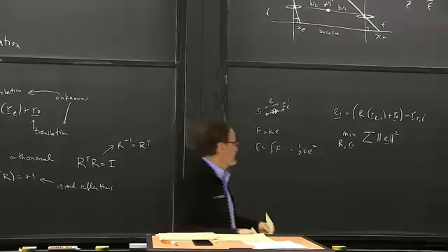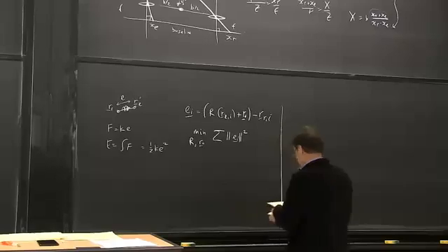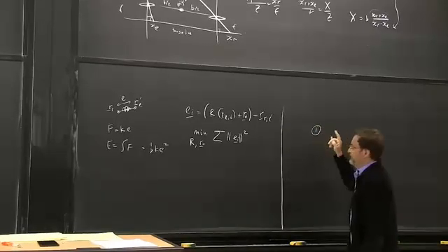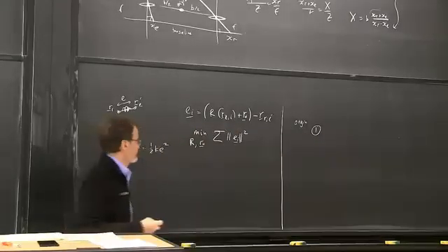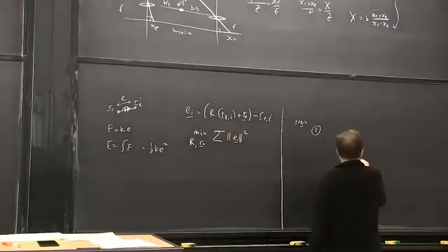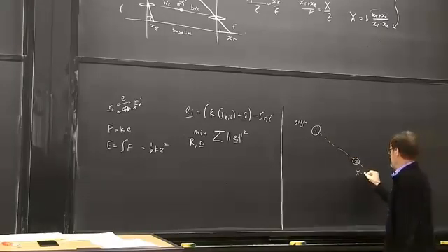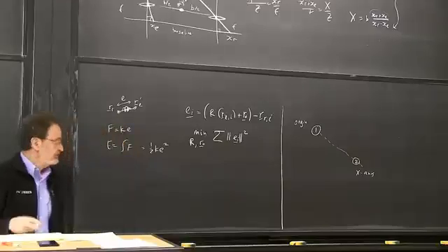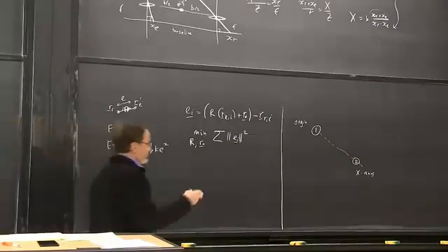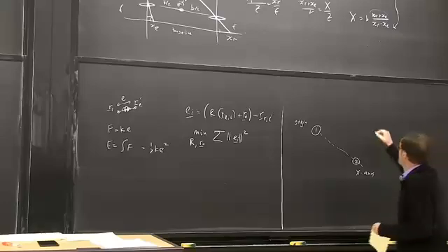And so here's a way of taking, say, all of the left points and constructing a coordinate system in it. So let's suppose we have point 1 here. So this is a measurement of some point, and we're going to use that as the origin. So out of all the points we've measured, we pick one and declare that to be the origin. Okay, step one. Then we look at a second point, and we connect these two by a line, and that's going to be one of our axes. Now, the separation between 1 and 2 won't be a unit, so we don't use the actual difference between 2 and 1 as our coordinate. We normalize it.